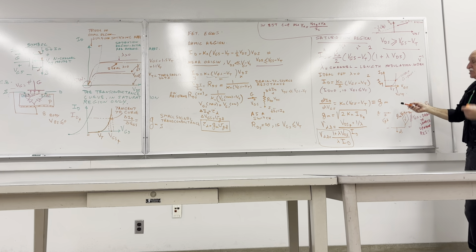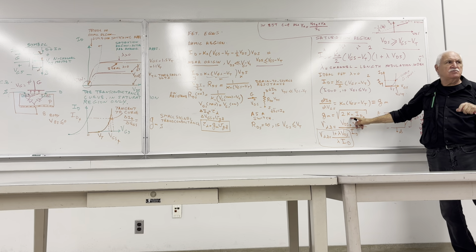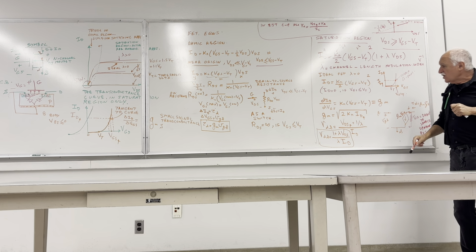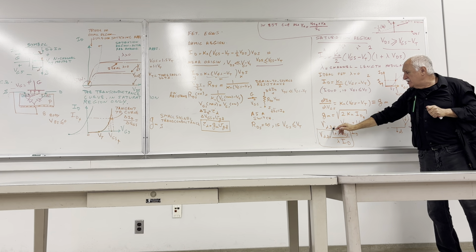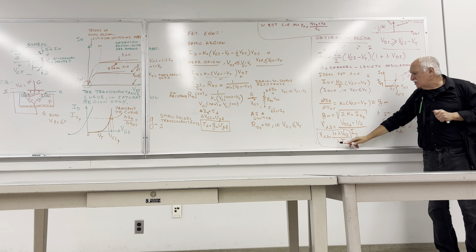And Kn is the conductivity constant, which depends on the geometry, area, mobility in the semiconductor. This will be given to you. Kn will be given to you. And in case there is a lambda that you know, then it can be incorporated in this equation, knowing the Q point, knowing its ID, knowing its VDS. You cast it into this formula here, VDS and ID, knowing lambda.